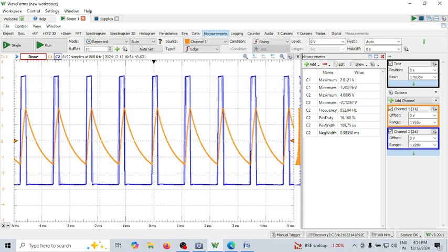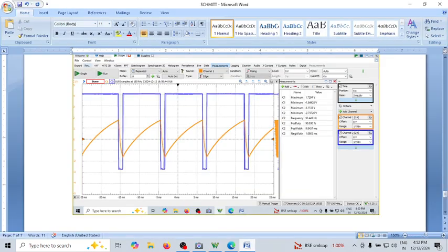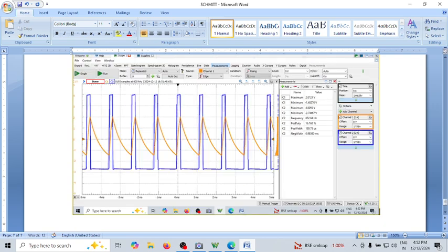So you can see the duty cycle is hardly 16%. So where is 90%, where is 16%? Because my RT on is very small. So this is the positive duty cycle. I will take a print screen of this and I'll just go back to this. This is for an RT on of 1.5k. So this I'll paste it now. So now you can see these are my values of different readings.